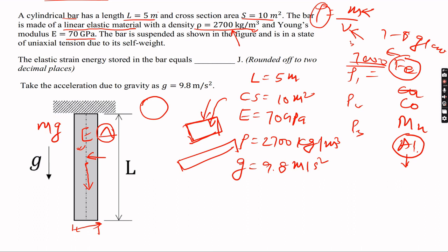Okay. So now come to the question. We have to find out the strain energy stored in this body due to self weight. Does anyone know what strain energy is? First of all, we'll calculate what energy is. Energy is nothing but force into displacement. You have written this: force into displacement is energy, the work done. This is the work done, integration from some value to some value.